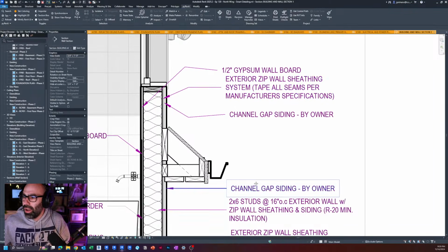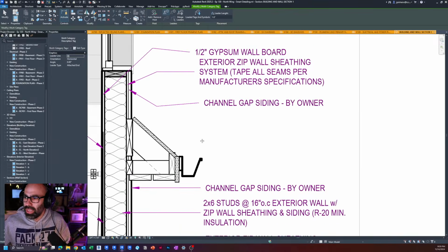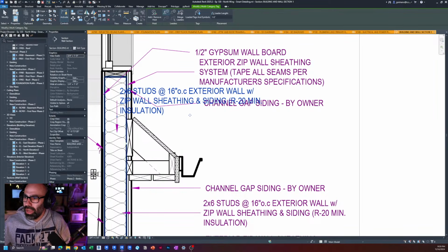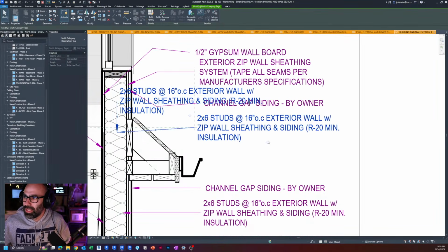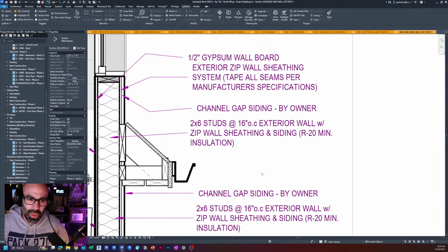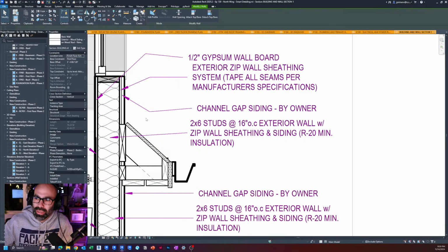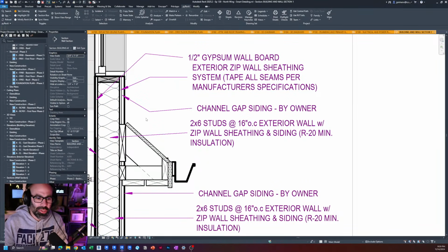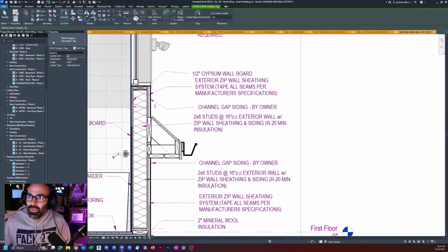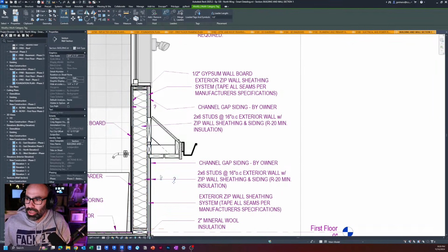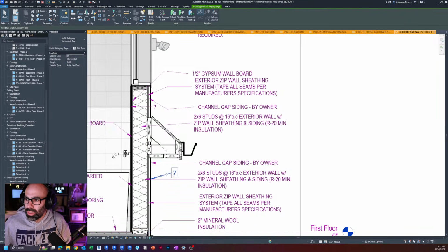But I also can click this guy, which is the multi-category tag, and I can tab to the wall and put in a tag that says a system thing, like here's the overall wall system, right? So by combining these two tags within this element, you can now start building this information. Now, right now, this is using the description of the element, and I'll show you where that is. I have one more that I've added, which is also using the comments, which is an instance parameter, which you guys may know. And so this one, there is no comment in here.